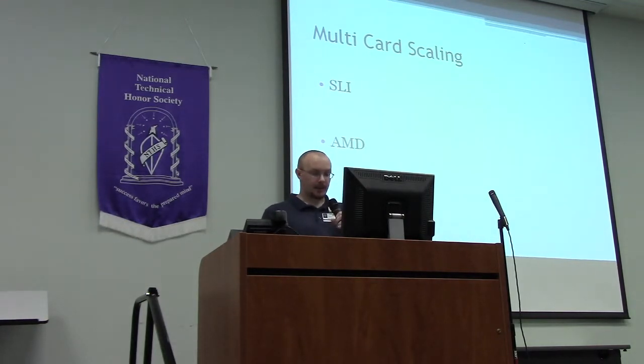Some video cards can be linked together to allow scaling of the graphics processing across multiple cards. This is done either using the PCI Express bus on the motherboard, or more commonly, the data bridge. Generally, the cards must be of the same model to be linked, and most low-power cards are not able to be linked this way. Cards from different manufacturers cannot be used together for multi-card scaling. If a video card has different sizes of memory, the lowest value will be used, with the higher values being disregarded. Currently, scaling on consumer-grade cards can be done using up to 4 cards.